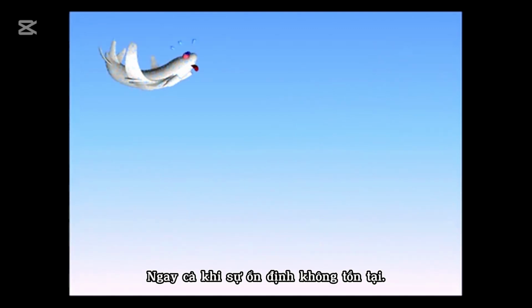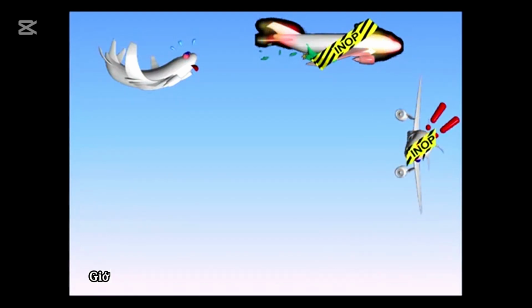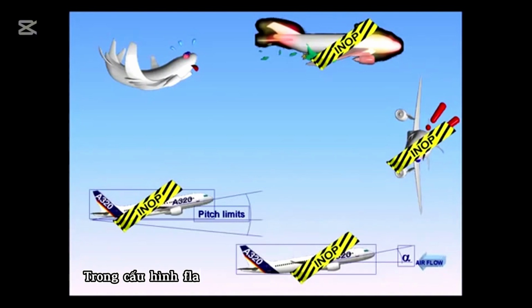Even if stabilities do not exist, the airplane is still protected by load factor. Load factor limits are the same as for normal law. Clean, plus 2.5, minus 1.0. Flaps extended, plus 2.0, minus 0.0.